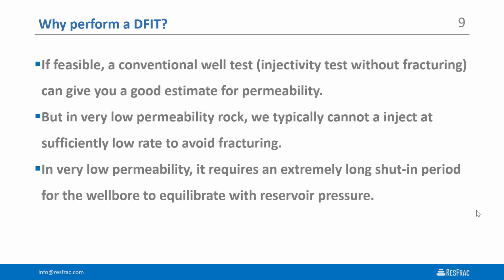You might also ask, well, why do we need to do this to get pore pressure? Why don't we just drill the well and monitor pressure? And that's because it actually can take a really long time for the pore pressure in the wellbore to equilibrate with the pore pressure in the formation if the permeability is really low. So if you create a hydraulic fracture, you generate a whole bunch of fracture surface area that can accelerate leakoff, and it allows you to more rapidly get to the point where you can actually estimate pore pressure.